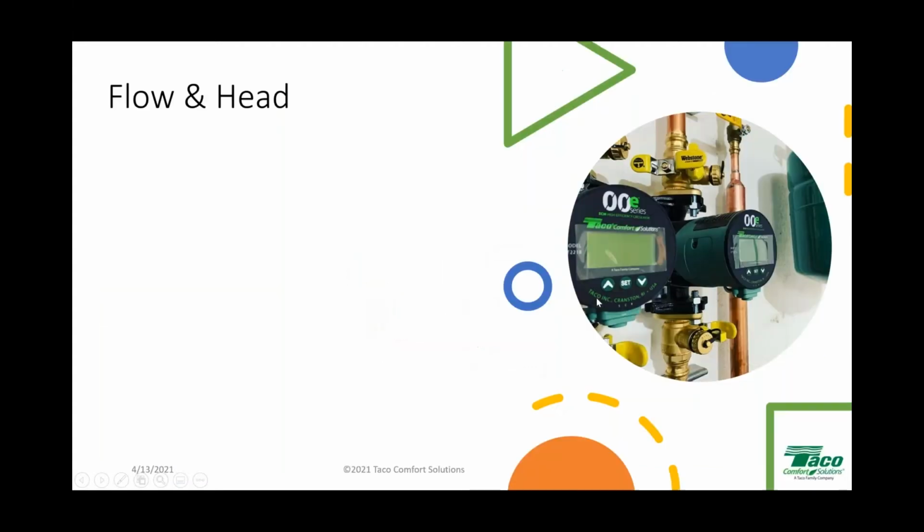Well, let's get started here then. With variable speed ECM circulators, it all starts exactly the same place as it would start with any fixed speed circulator. It starts with flow and head. You really need to know the flow rate that you need for the application required, as well as the head loss or the head pressure loss for said application. So we need to know the flow rate and we need to know the head so we can fine tune these circulators, because they don't fine tune themselves. That's very important to understand.